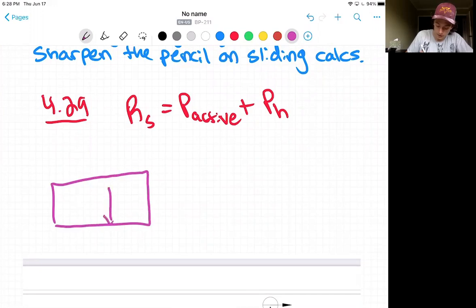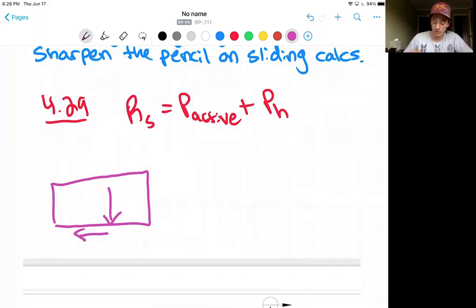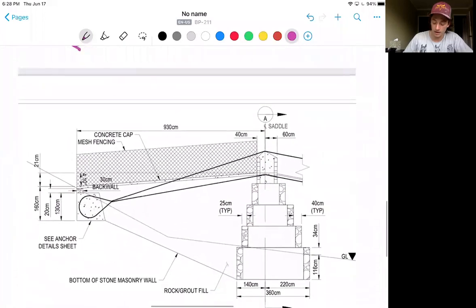With some force, some frictional resistance, etc., etc. Forces are transferred from the anchor through the ramp walls and into the tiers. We don't actually check or rely on these forces. However, we cannot discount them when we're viewing the entire abutment as a block.